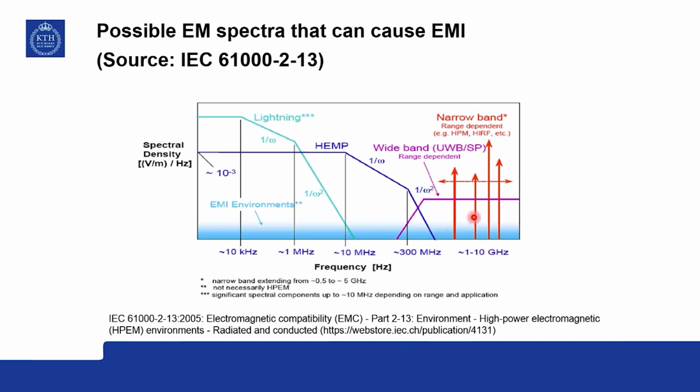And cell phones operate in this kind of range, where they can be susceptible to these types of frequencies. So, basically as far as noise is concerned, the whole spectrum starting from sub 50 hertz, even DC, to several gigahertz are possible candidates for EMI problems.